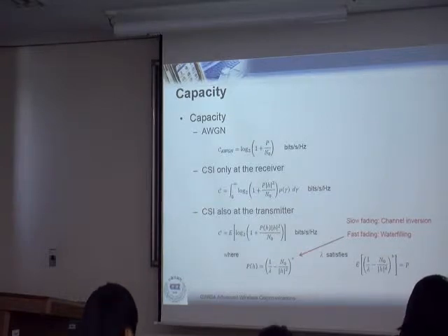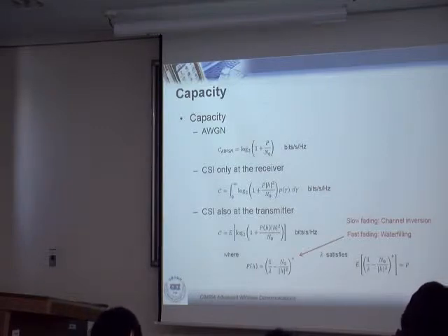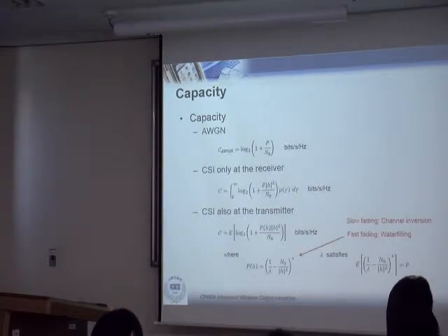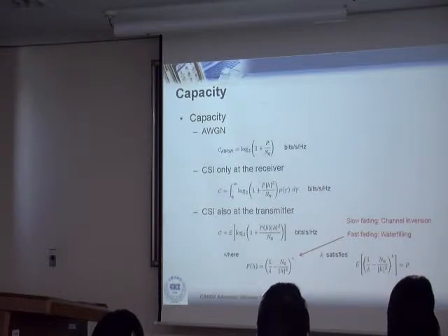When you have a deep fading, I'm going to assign a big power. When I have a small channel gain, I have a big power. When I have a high channel gain, then I assign a small power. So this is this picture, the yellow one. Let's talk about how much power I assigned. But that is inversion of the channel. You see what I'm saying?